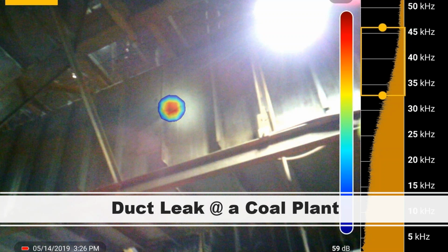If you've got a vacuum system that takes out debris from a laser cutting system and something is not working on that and it's not pulling the debris out properly, you could have quality issues. So think about this a little bit differently. Think about any kind of compressed air, compressed gas, or vacuum leak that might either cost money or cost quality or performance issues. And that's where you're looking when you're walking around. If you're hearing hissing when you walk somewhere, you've got something.